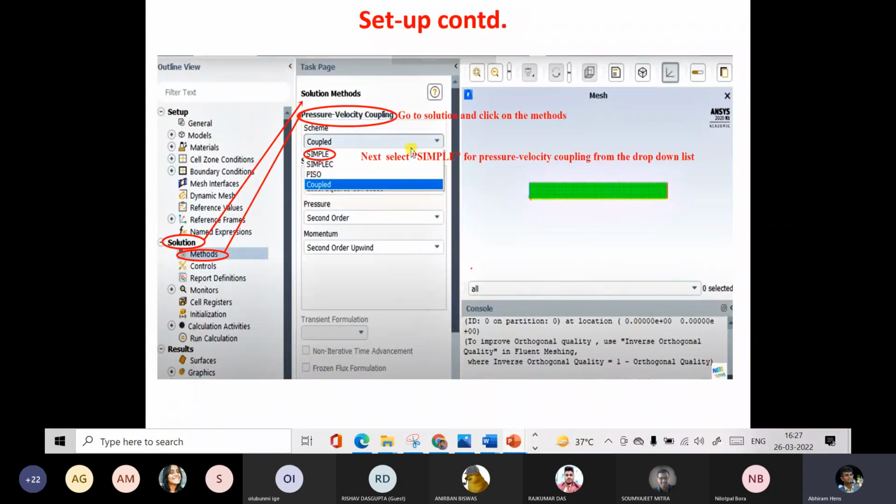there is velocity and pressure both. So UVW three directional velocity will be there. If it is 2D, at least UV will be there and pressure will be there. Now this pressure and velocity are actually interacting parameters. Okay, so pressure field has effect on the velocity field. Again, velocity field has effect on the pressure. Means both are actually linked, coupled. So this pressure velocity coupling is an important parameter. Okay, so that is the most tricky part of the CFD solver.